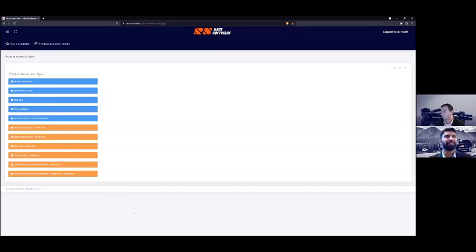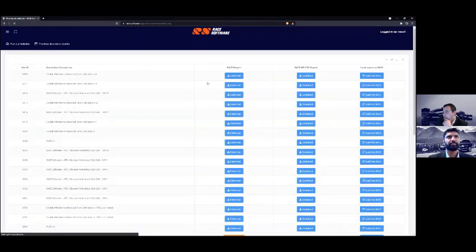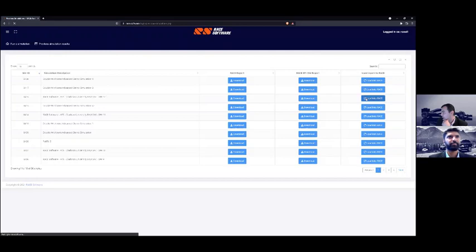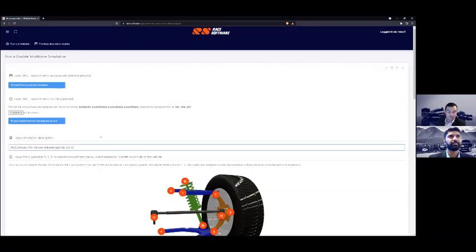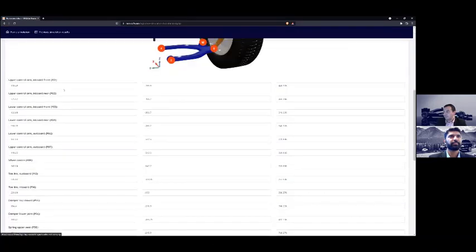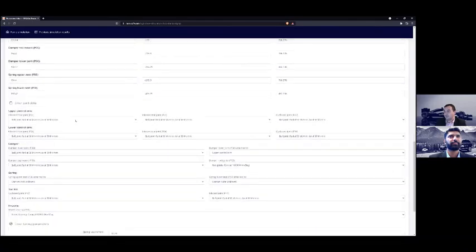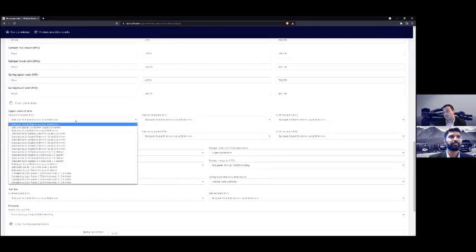Yeah. Brilliant. So for the first time that the simulation will load the data from a previous simulation. As mentioned, we'll be using exactly the Baja vehicle from the video with the data that has been supplied to us by ATS. You basically specify your hardpoint coordinates, X, Y, Z, and after that, based on our vast experience, you can basically choose the different stiffnesses at each pickup point.